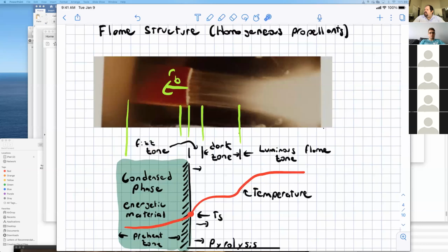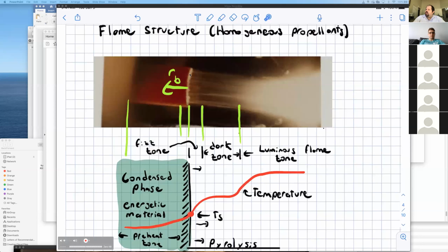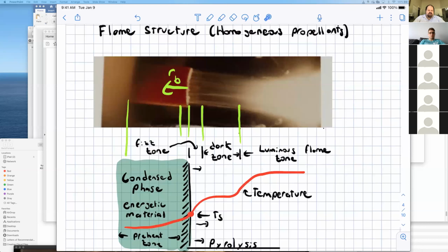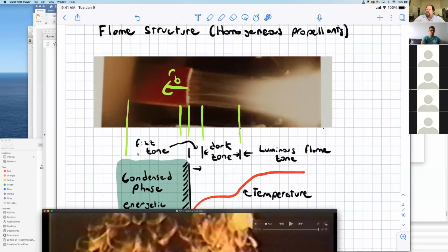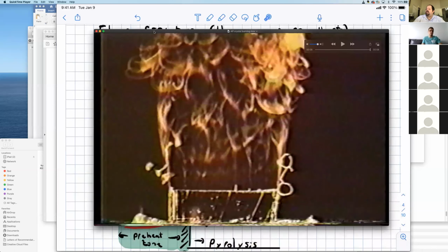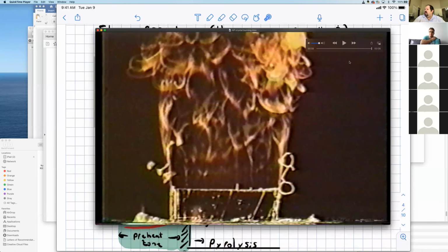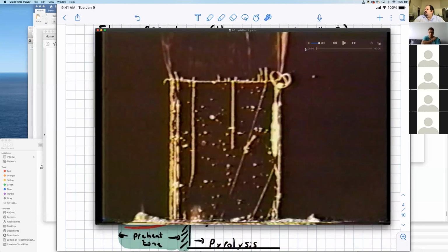So there's a burning rate inhibitor that is preventing that, because here, all we are after is just the steady one-dimensional burning velocity. In real propellant systems, there would be a flame burning down the side, and you would need to consider that in your rocket motor analysis. If you watch a movie very carefully with the AP, you can actually see that burning rate inhibitor. I don't know what it is for this crystal. It's something else. But you can see it sort of peeling off to the side and not quite burning away.